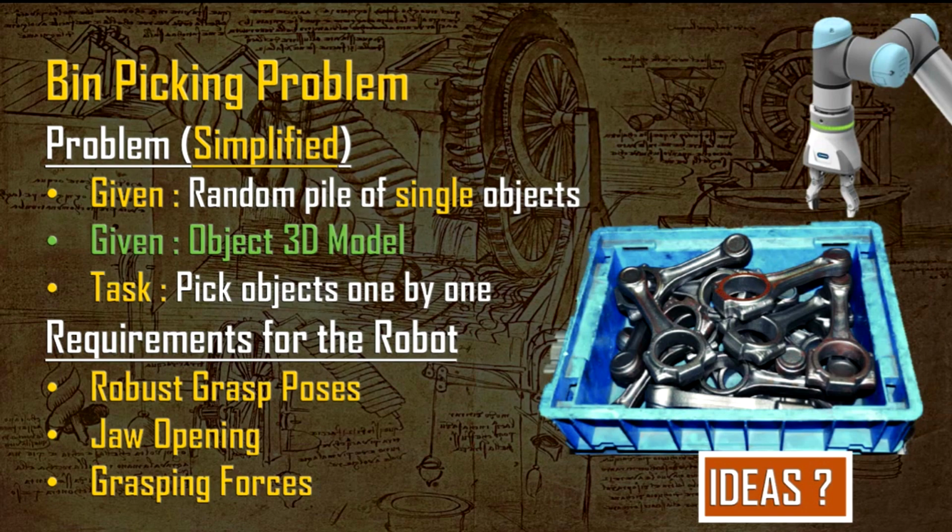There are multiple vision algorithms and ways. For example, in applications where bin picking is not involved and everything is sorted on the same level, yet with some requirements you can use 3D depth images to identify the orientation, not just the position and location, but also how the object is oriented in 3D space. It is possible without 3D knowledge as well, using image stitching methods or PnP algorithms, as you said. But with 3D depth, we not only assess the depth of the object in the bin, but also identify the orientation, position, and how it is oriented in the 3D world.